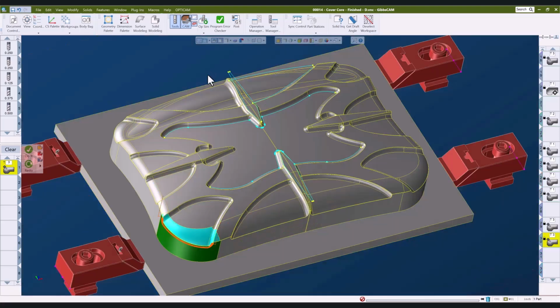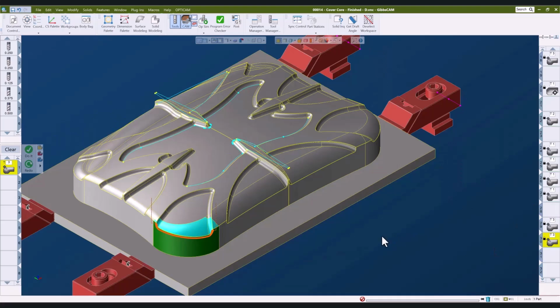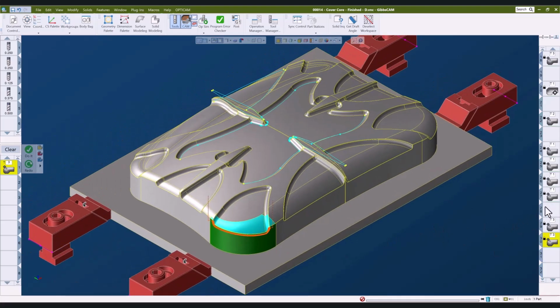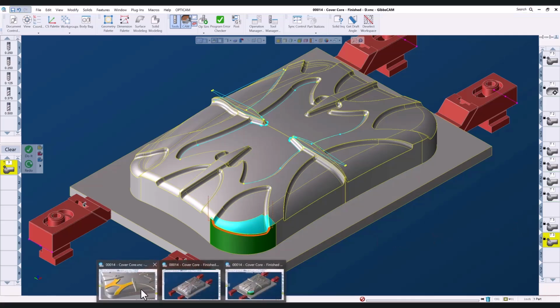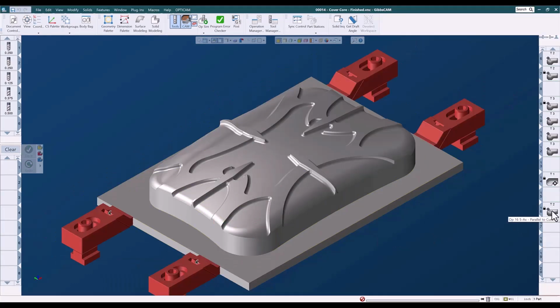Now, once we've developed toolpaths, especially if they're well suited to the parts we commonly manufacture, it can be really helpful to save the processes. Let me load this one up again. This is an advanced 3D in-curve flow using a 1/4-inch ball mill and with a step over of 20 thousandths. If I think this did a really good job on this part, and I'm likely to use this strategy with the same tool on something else, I might want to save the process.